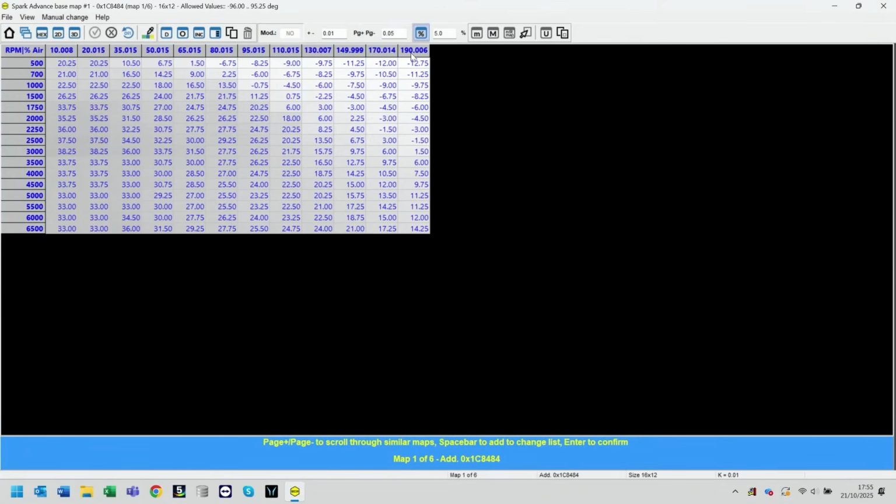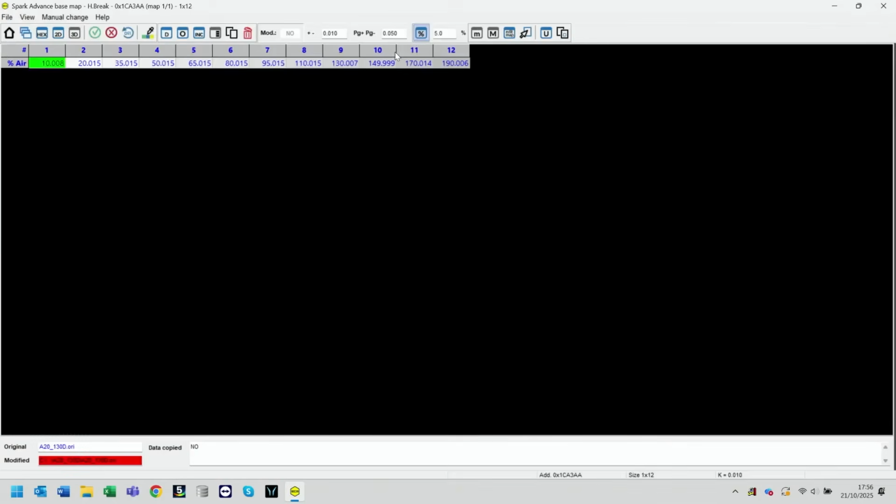The strategy here would be, if we went to 200% of air on our limiter, we would then have to data log and potentially reduce our values here to compromise the table at this point to make sure it's safe for 200% of air. Or we could move into our more intermediate and advanced strategy of starting to make changes to the axes and scale the axes up.